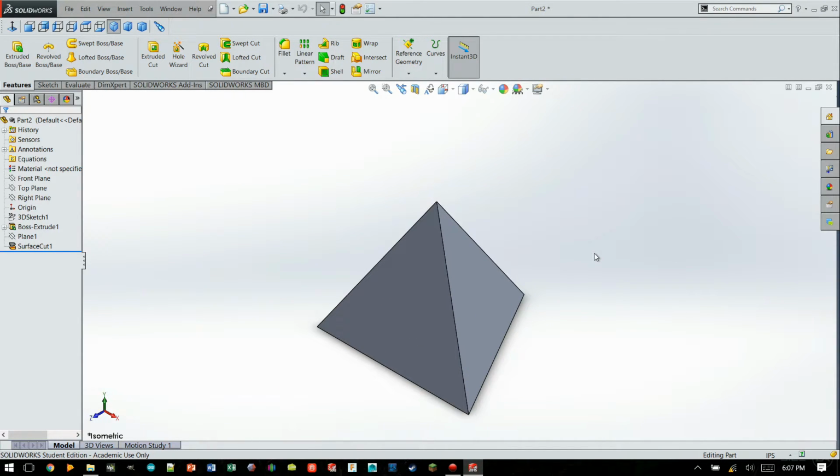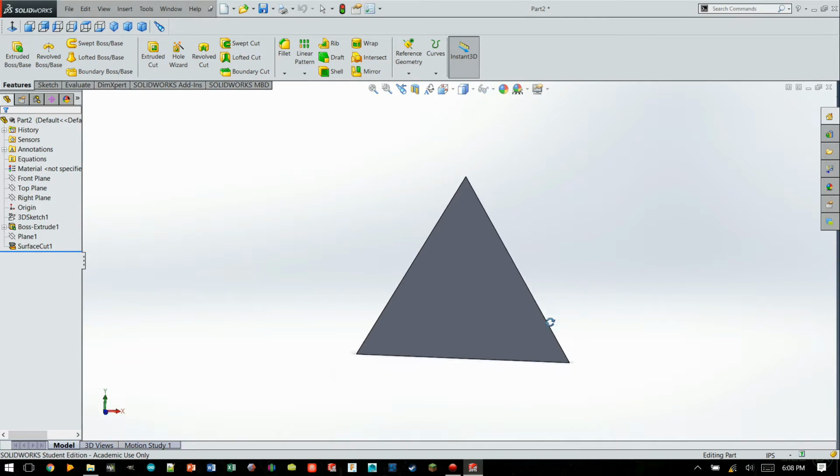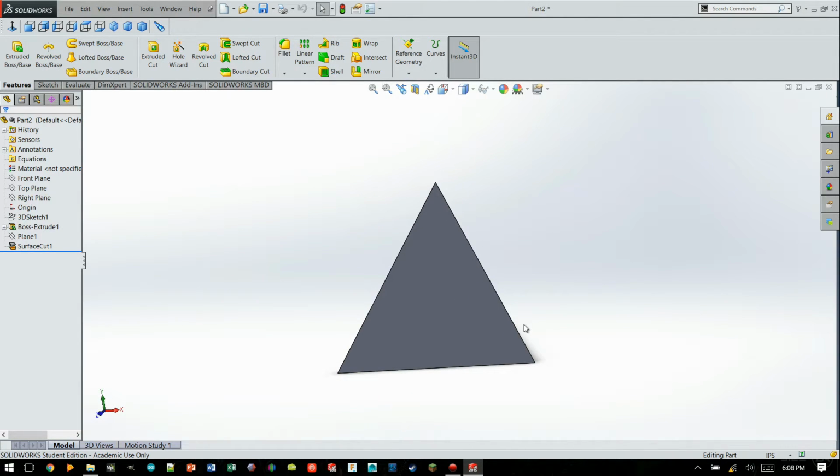Let's head on over to Simplify 3D and get it queued up to print. So with this model, it's kind of cool. We can actually print this in vase mode. For those of you that don't know, vase mode allows you to print a continuous outline of your part. So you end up with no infill and a very, very smooth surface on the outside surfaces. So since this part is greater than 45, we're able to actually just print straight up with no issues at all.